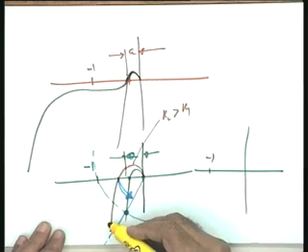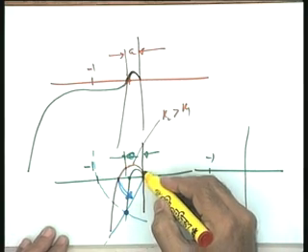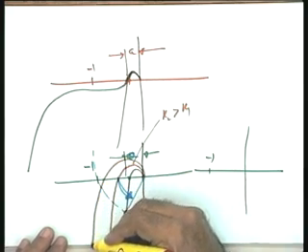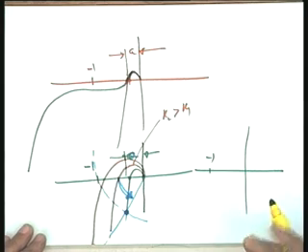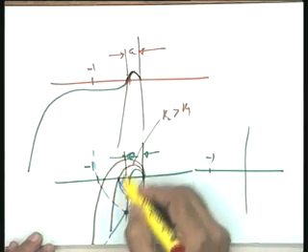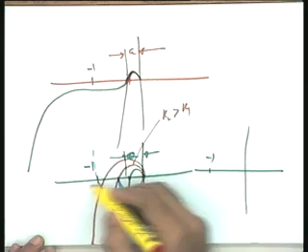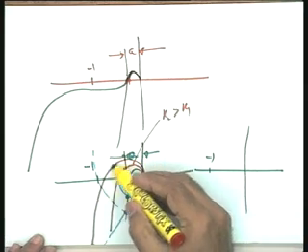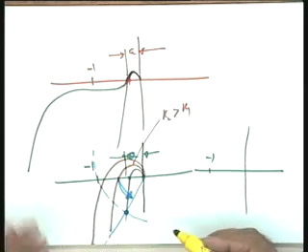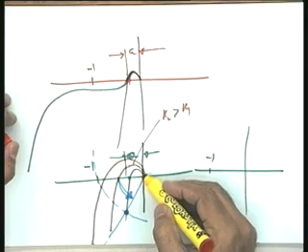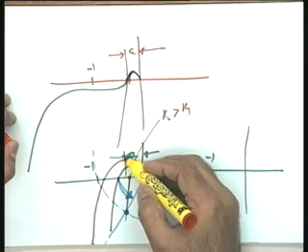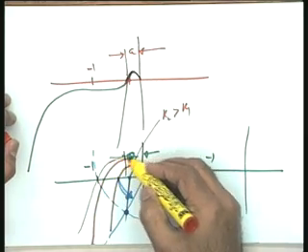Keep all the polar vectors, only change the magnitudes. You further increase your magnitude, the plot will be like this. It is the same type of plot, the only thing is that its magnitudes change, and therefore the plot goes this way. So, it means there will be an increase of gain which will slowly take it through the minus 1 plus j 0 point.